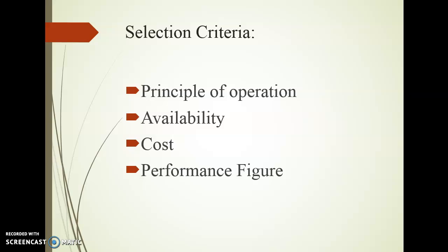The characteristics include the response time, recovery time, sensitivity, whether our chosen transducer is sensitive or not, and the input operating range of the transducer. All these come under the performance figures. On the basis of the above, we can choose our transducers for our applications.